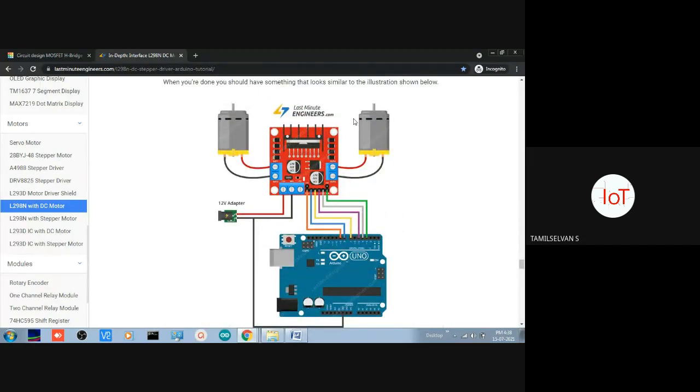Okay, so how your real time circuit will be working will be shown here. So you'll be given one controller. Definitely we need to direct the motor, or direct the vehicle, with the help of some controllers. So here it will be taken as an Arduino. In this case, Arduino will give a voltage rating of 0 to 3.3 voltage to this particular board. So we know very well these 2 motors will never run with 3.3 voltage. It requires at least 9 voltage or above. Okay, then only the motors will start rotating.